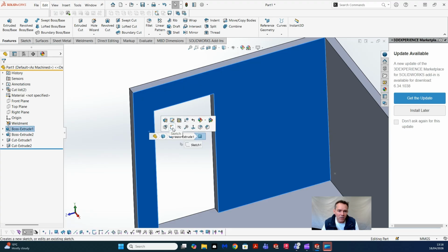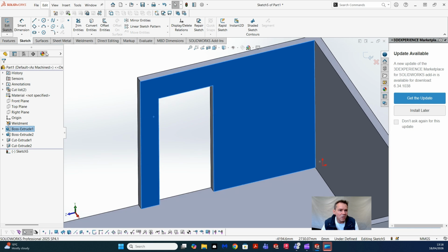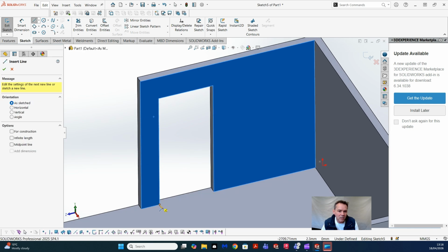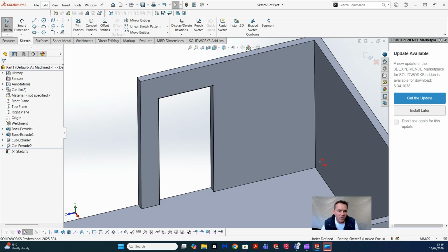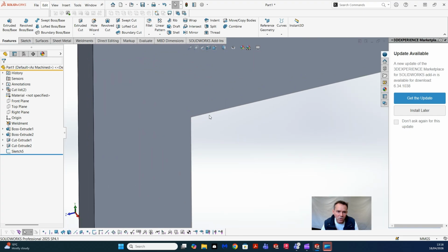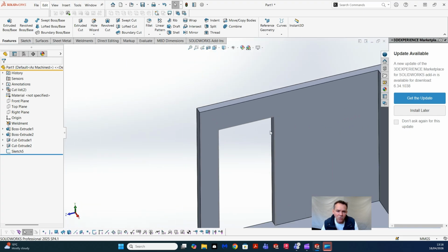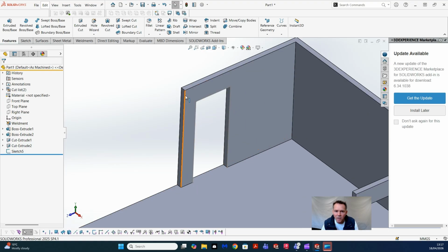First thing we might want to do is create a door frame. So we'll create a sketch to start on this surface, and simply pick up all these points with our sketch here. And that will be our first sketch. So we'll exit sketch, and you'll see if you zoom in, there's a grey line here. This doesn't show too well on the grey background that's already there, but there is a grey line. Otherwise, you'd see it all highlighted with the black lines.